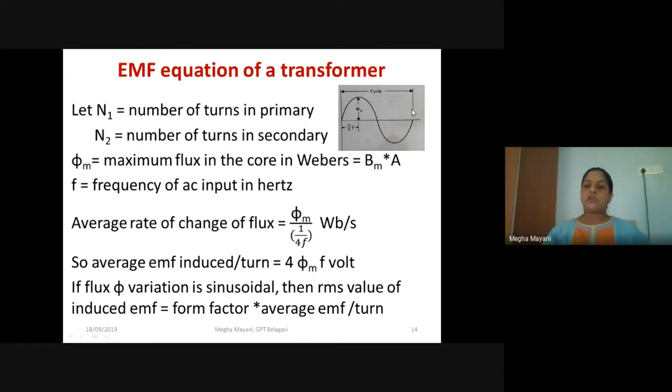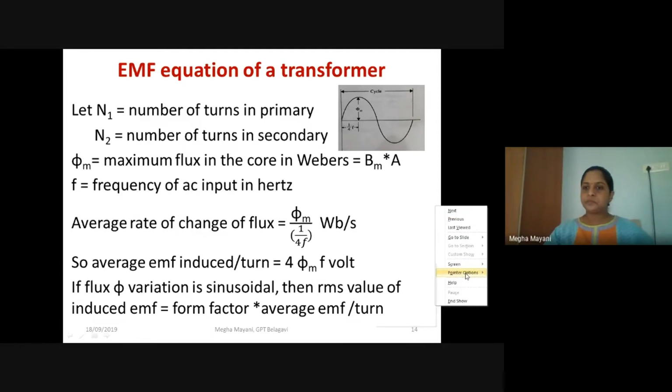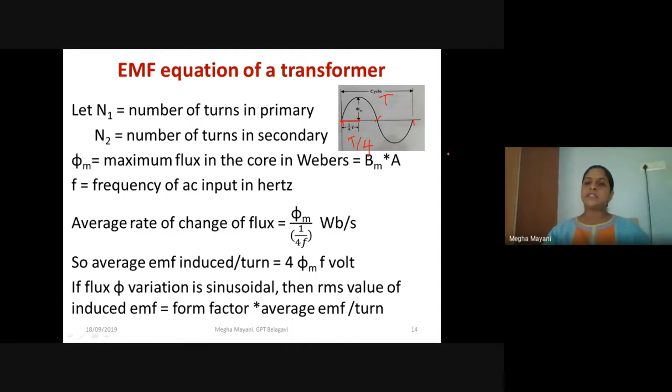So it will be also sinusoidal. So the variation is proportionate to the supply voltage what we have connected. Now the maximum flux reached during the positive alteration will be say phi m, and that is exactly, friends, look here, this is one cycle I have considered. So this is corresponding to time period T, and this will be T by 2. So if you consider the duration for maximum flux, it occurs at exactly T by 4 seconds time.